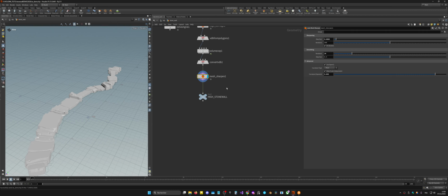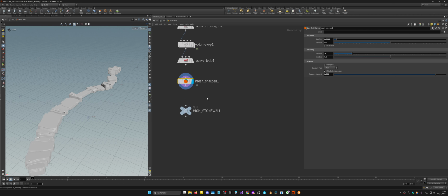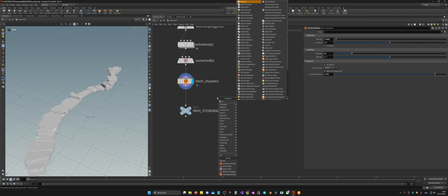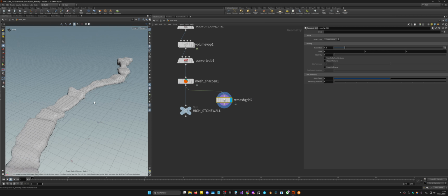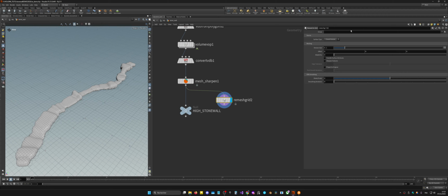So to create the low polygon, I tried many things. I think the flow I'm showing is the best, according to me, for sure. So I use voxelize from the high. So I will go to voxel and back to polygon again. As you can see, it's now mid polygon. I want to keep it a little high.